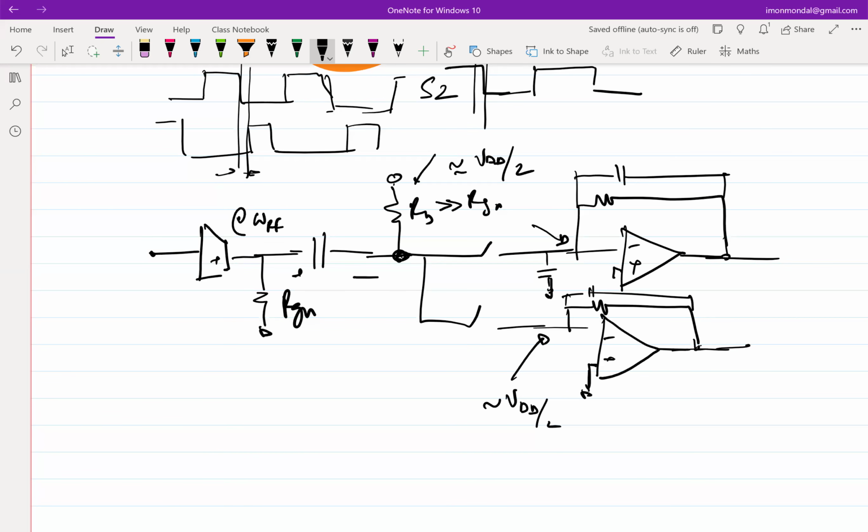Okay, fine. So now before I move on, any questions on this? Yes, a forward bias issue can come in. Whenever you have a PN junction, you can have a forward bias issue if you're not careful, but the condition need not necessarily be the same for which the forward bias happens. Source and body are? What about the drain side? Can happen, right? So there is another issue why it's shorting the source and body or the source and drain.